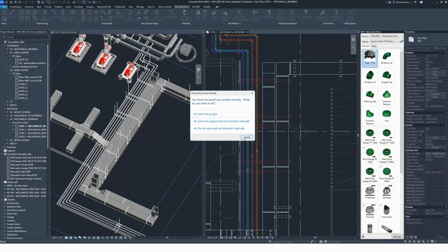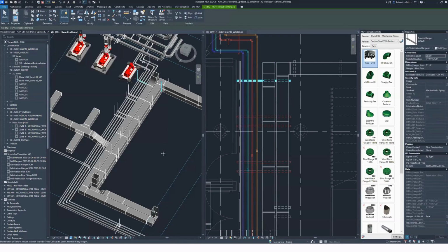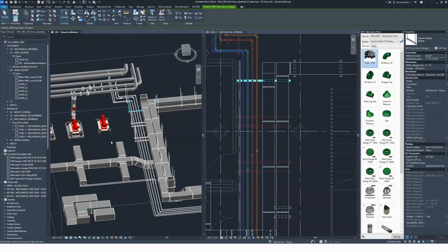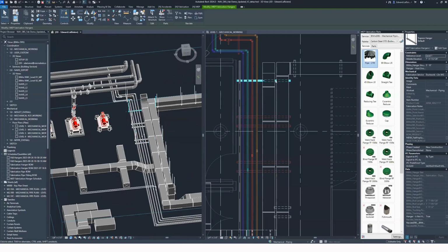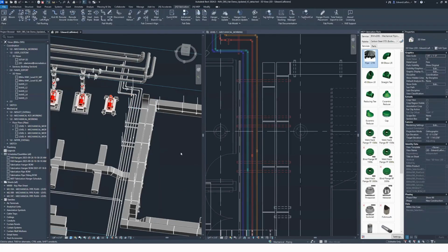And there we go. Stretched right across, letting us know that all those things are updated. And there is a slight catch because it can't be this awesome. If we do those extra large trapezes, we do have to unhost them for them to work. If they do remain hosted, you can't extend them out this way. A lot of stuff ends up breaking. So small catch to go ahead and actually properly support our elements though.